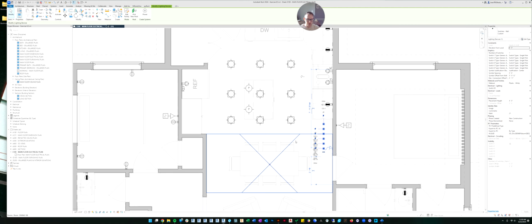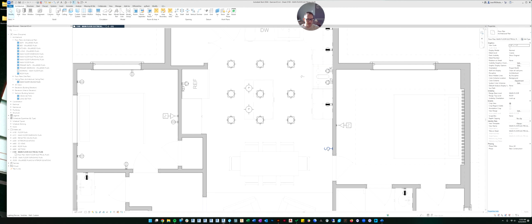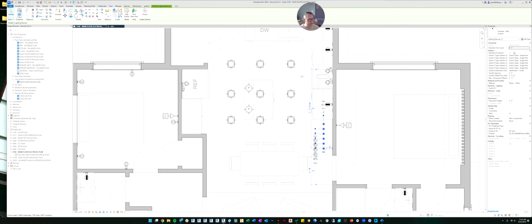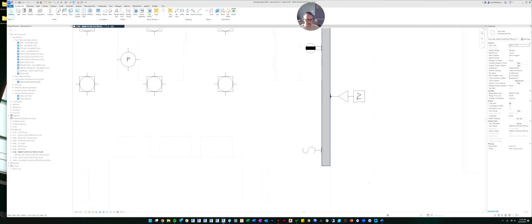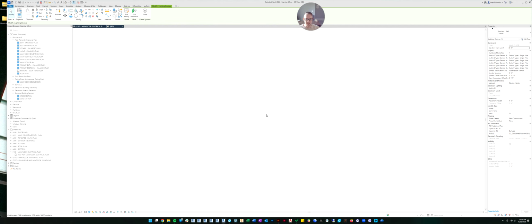And then you'll notice if you click on the switch, instead of picking from the family types and picking dimmable, 3-way, 4-way, single pole, they're all built into the switch. So if you just click the switch over here, you can have up to 6 switches in one spot. So let me show you what I mean. We need to see this in 3D in order to understand.